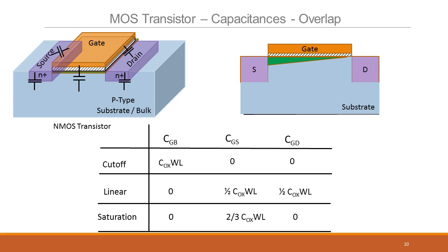Now, just before we go to the PN junction diodes, the drain to bulk and the drain to source, there's one small thing that we need to cover, which is called the overlap capacitance. These regions here, the gate to drain and the gate to source, though we have drawn them perfectly ideal, fully aligned, they're usually not.